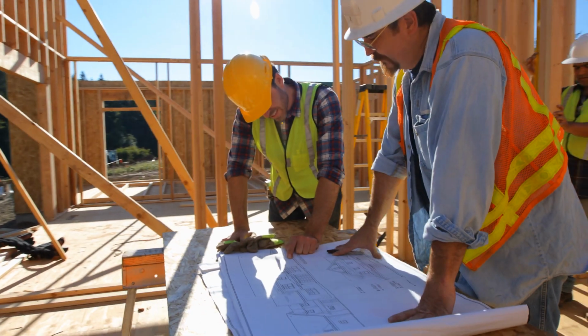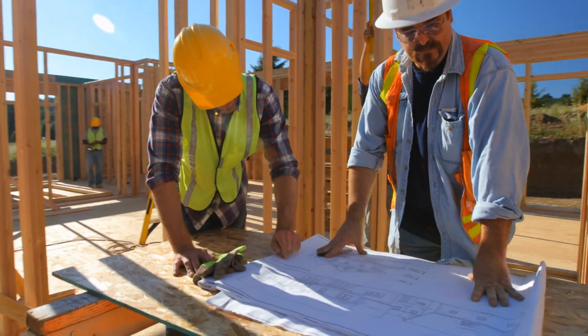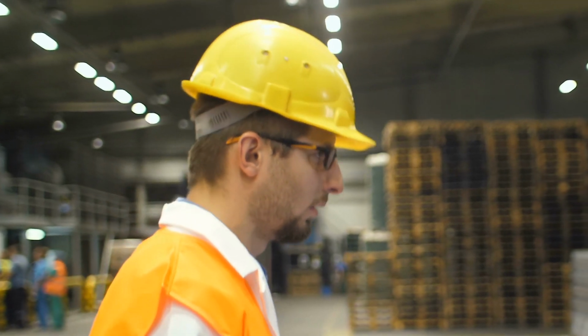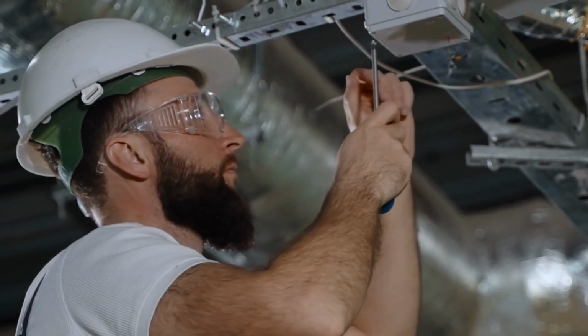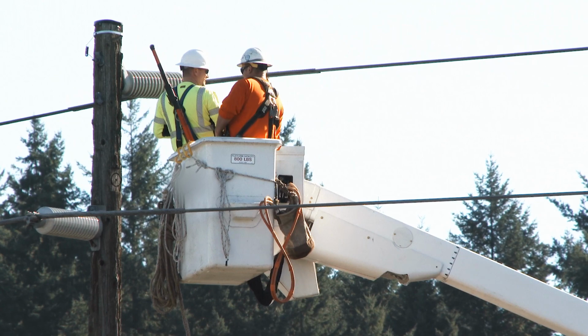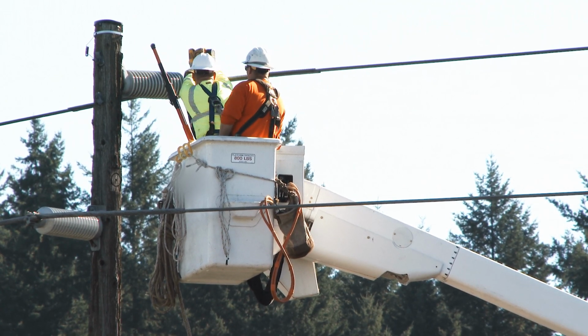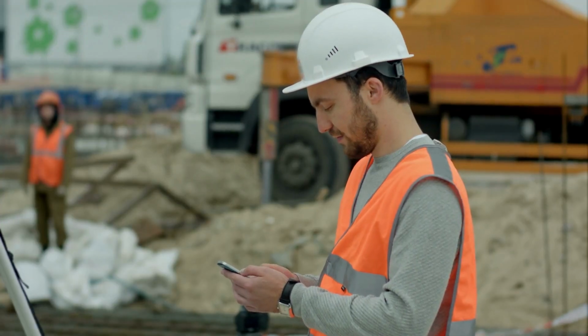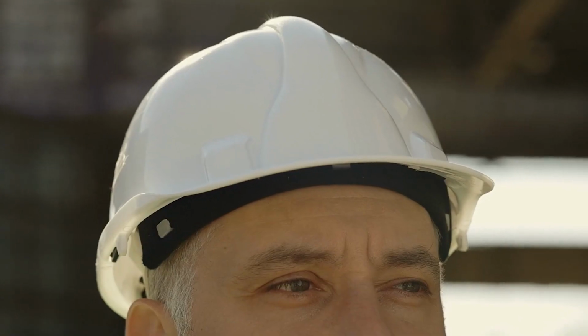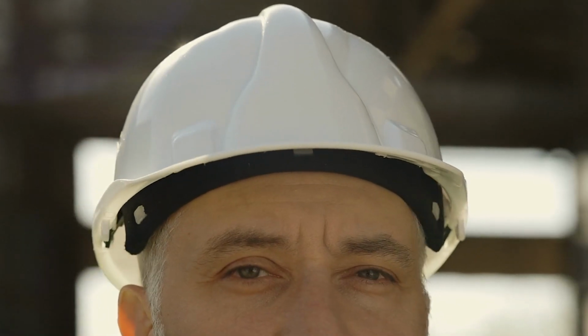Hard hats need to be designed with a tough outer shell and a shock-absorbing lining that includes a headband and straps that keep the shell away from your head, reducing the impact of a blow. Oh, and for those of you working with live wires, your hard hats should also be specially designed to protect against electrical shocks. But wearing the hard hat isn't enough. It should be in good shape, fit snugly, and be worn with the bill forward for maximum protection.